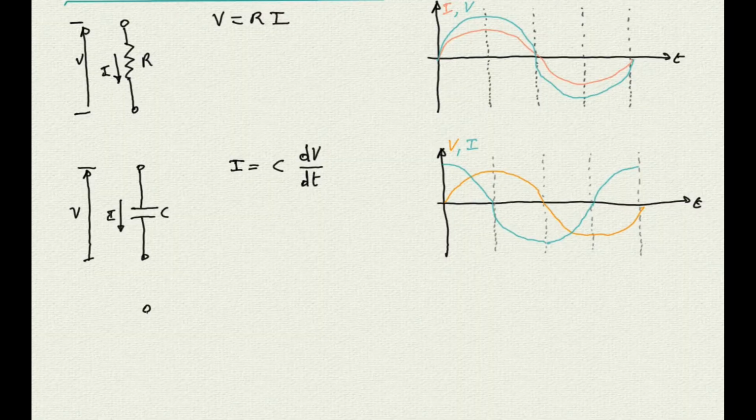We know that the inductor stores energy in a magnetic field, which is directly proportional to the current flowing in the inductor. And we know that if the current changes its value, the inductor counteracts the change, generating a voltage meant to keep the current flowing at that same rate. Therefore, we can write that the voltage at the inductor leads is proportional to the inductance L and to the speed at which the flow of current changes.